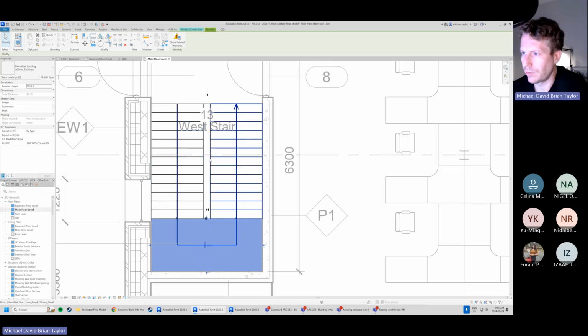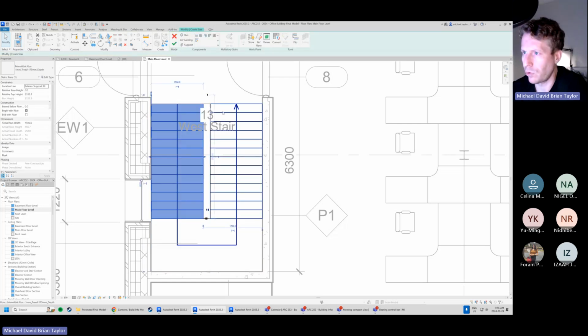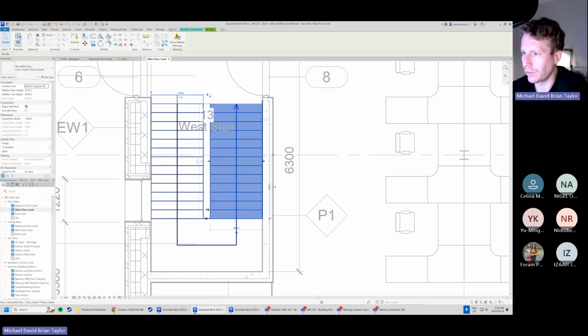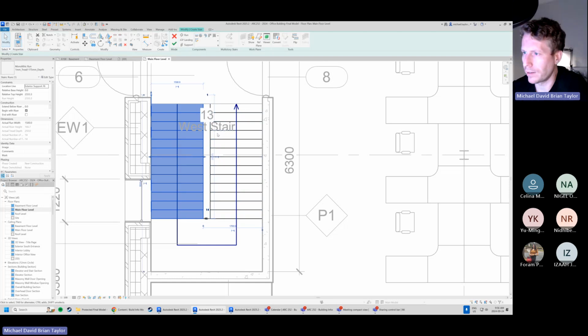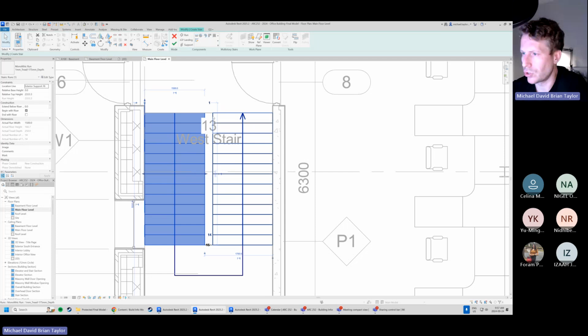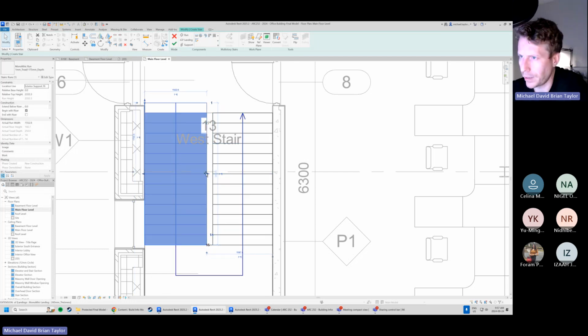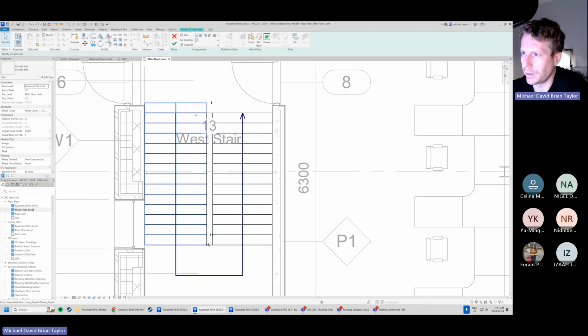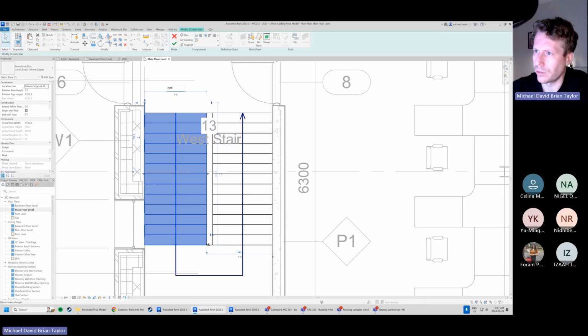And then the middle zone here, if we do want to modify how wide this little zone is between the inside face of the stringer and the inside face of the upper stringer, we can do that as well by either dragging our little shape handles, or typing up here in our 1500, right?